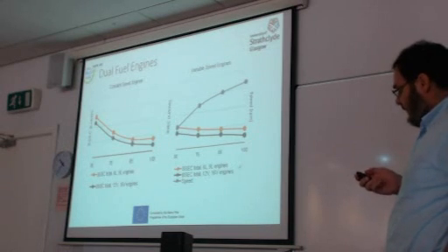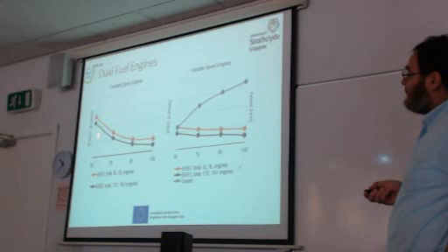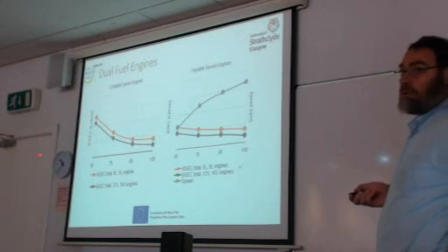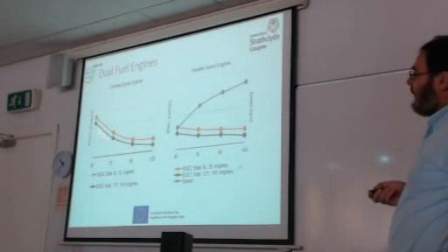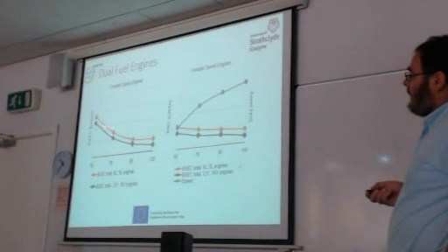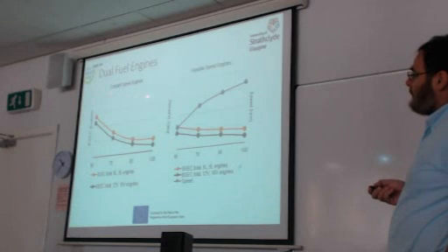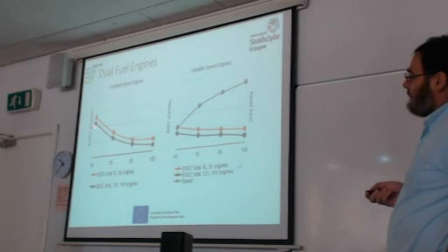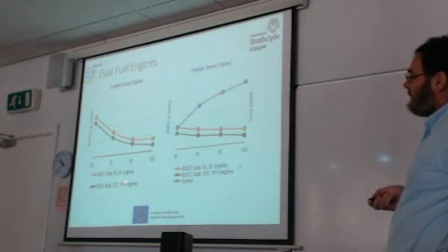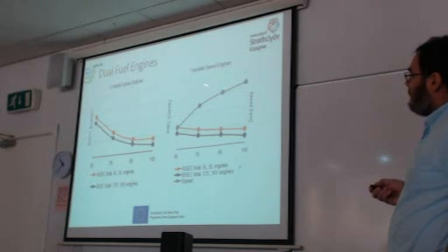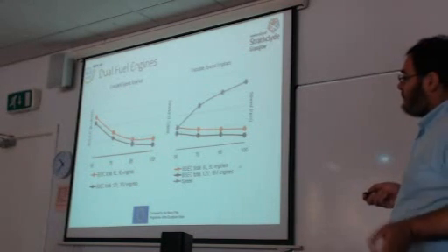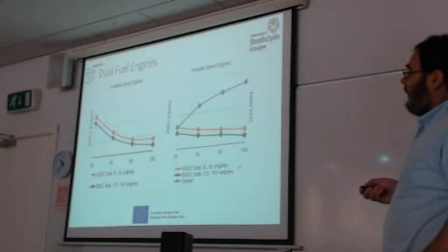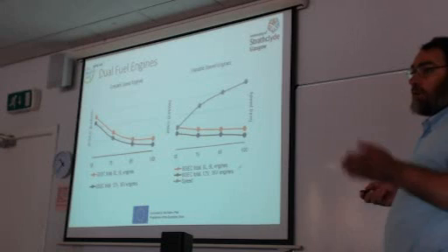So that's the case with the two-stroke gas ignition engines. What we have here, so these are figures provided by Wärtsilä, and this is brake specific energy consumption. It is actually proportional to brake specific fuel consumption, kilojoule per kilowatt hour. So what we have here, we have the engine, this is for constant speed engines, the brake specific energy consumption for various types, for inline engines and for V engines.